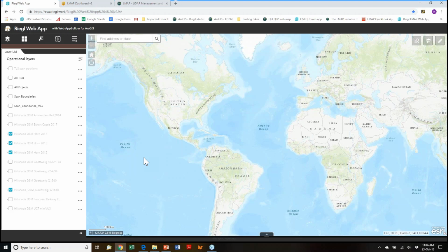So we've got all these LAS files now, and all sorts of metadata, could be QC reports, could be all sorts of things, including imagery. And we're going to start making things out of those. For example, we want to be able to create tile boundaries and project boundaries, possibly create some 2D derivative products like your digital surface model, potentially hillshade, the digital terrain model. We're also very keen on this I3S scene layer package or web scene format. So we're going to automatically create that file format, again in Pro, and then we're going to take all that and publish it into either ArcGIS Online or Server.